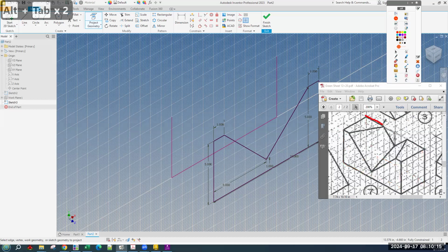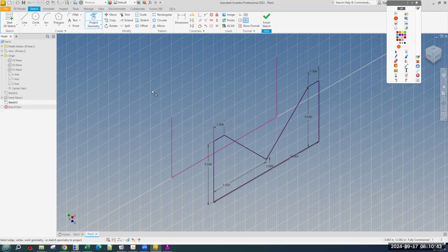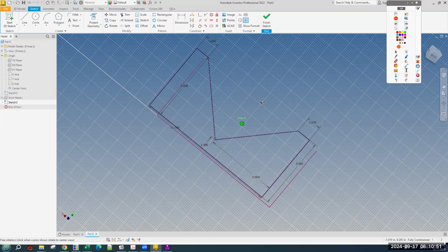And now we just have 3-inch lines that come in this way, which I'm looking at a different corner, but they're 3-inch that way. And they connect to a point that is centered and 2 down. So we'll do another work plane that's right on the center point right here, but 2 inches down, and then we can connect over. And once we have 2 closed loops, we can loft the 2 closed loops together. Okay, so we are sketching here. We're still in sketch mode, and we just need to draw the lines.